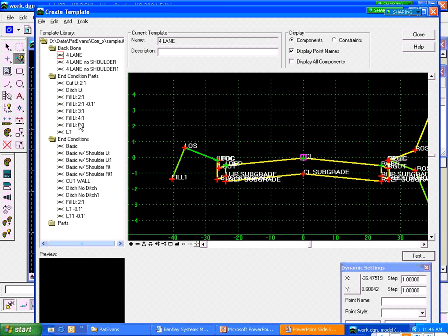I have our left ditch that I just showed you. So we're going to take it and add it onto that fill point right there. And then also, that'll solve it if we have a situation where it's draining towards the road. If it's draining away from the road, I've got a 2-to-1 slope, and this one's just a straight 2-to-1 slope with an infinite end condition on it.